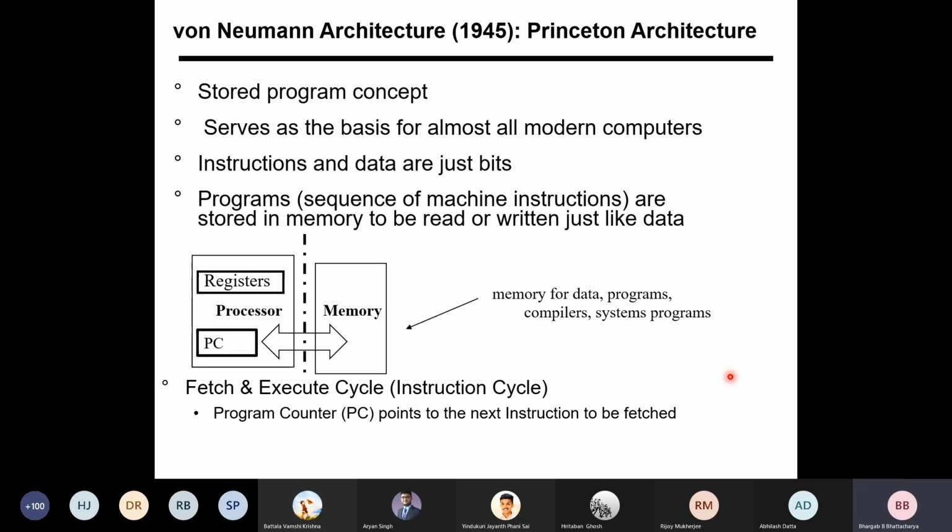So you have understood the basic concepts, how the execution should be continued one after another. And now we would realize how I would distinguish between instruction and data, and if data, what type of data? If it is an instruction, then in the instruction there would be certain specific bits reserved for it. These are called opcode or operational codes. And these codes will tell you what sort of instruction it is, whether it is an add instruction, or a logical AND operation, or a shift instruction, or a branch or if then else.